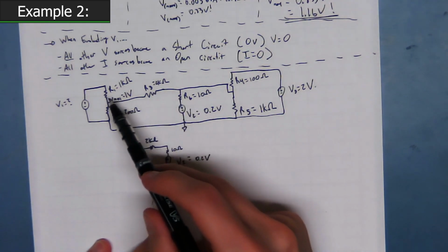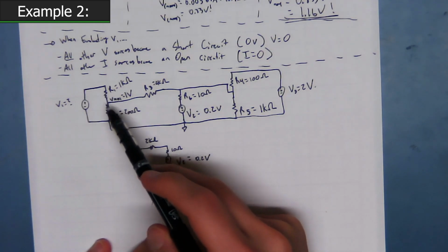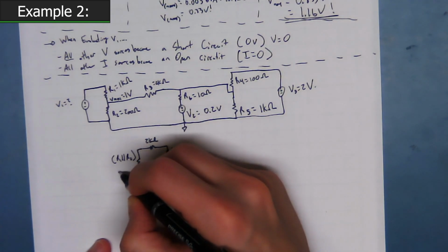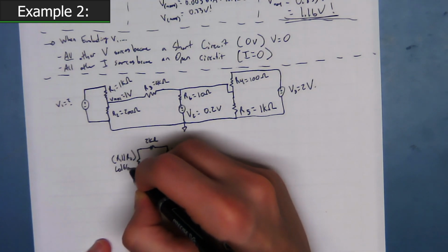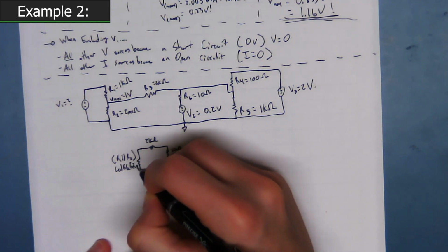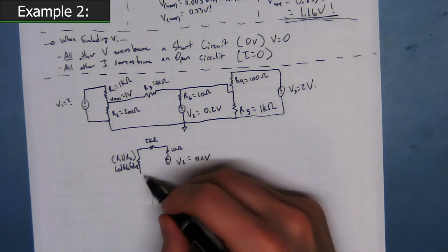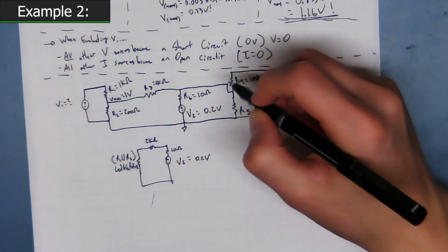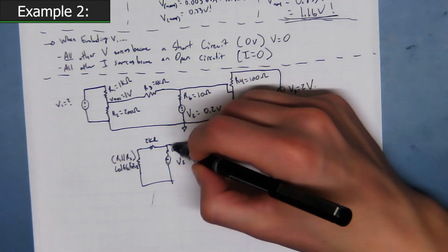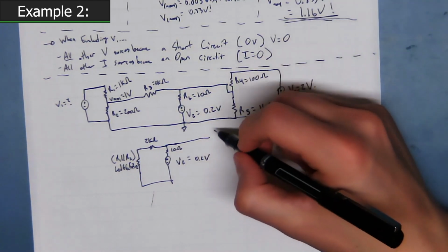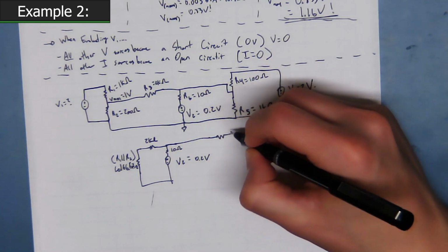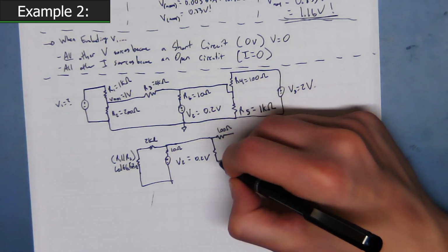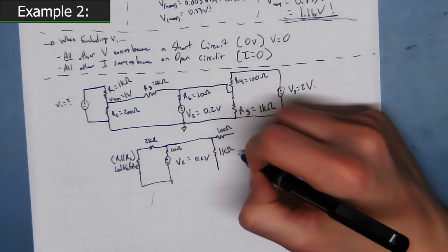Over here, we've got this parallel combination, because that's 0 volts, right? That's a short circuit. So these two are in parallel. This is R1 parallel with R2, or 166.67 ohms. Okay. Now what? We've got another resistor here. We've got 100 ohms. Yep. Just making sure I'm drawing that right. Yep, we got 100 ohms. And in parallel, we've got 1 kilo ohm.